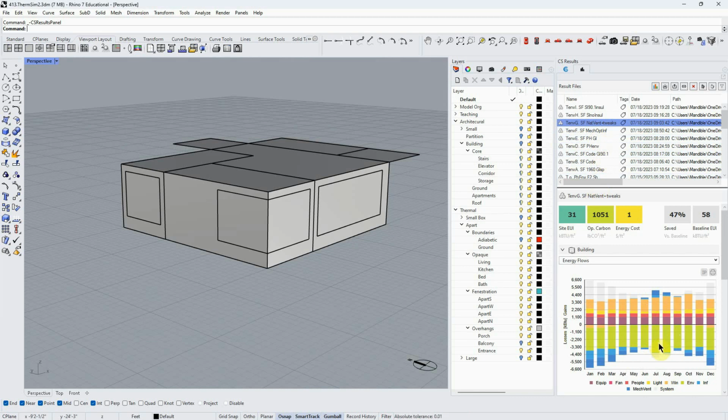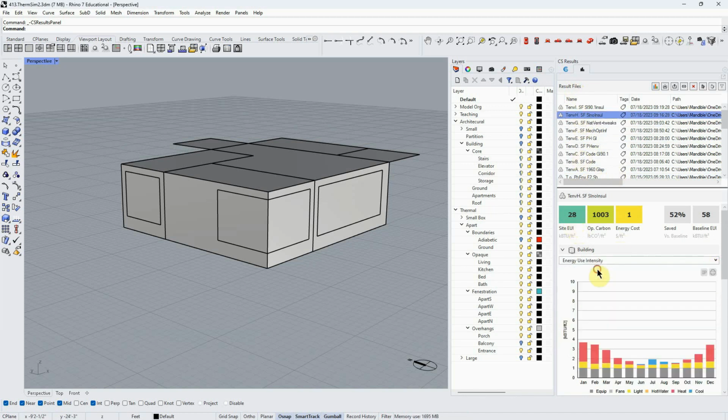So what would happen if we got rid of that insulation altogether and tried to pull even more of the heat out of the building in the summer? So I tried that, and I did actually lower fairly significantly my site EUI. Let's look at what other effects that had. So this is the one before with a little bit more insulation. Just look at the heating loads and the cooling loads. They're both going to go down.